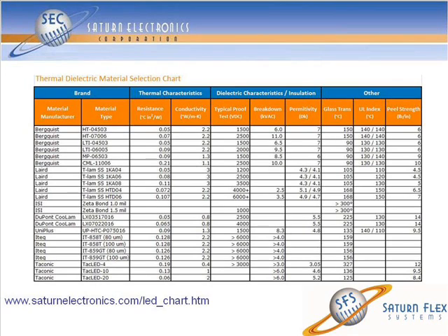I think one thing that's very important, a little bit on the fly here, is the intellectual presentation, where they had their testing values, B stage versus C stage. Their numbers with C stage, which is the cured material, the pressed material, came out much lower, I think a third of the conductivity value of the published data. As you do more research, I implore every OEM to ask their chosen material vendor, what is your data based on? Because in questioning, I found that sometimes some people are using B stage. And for those of you who don't know the vernacular, B stage is uncured material.